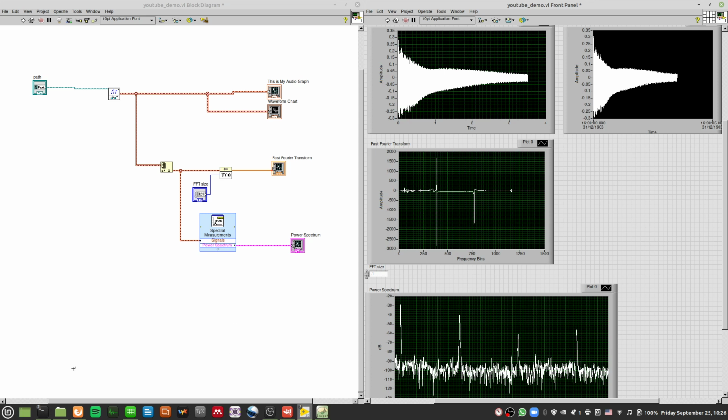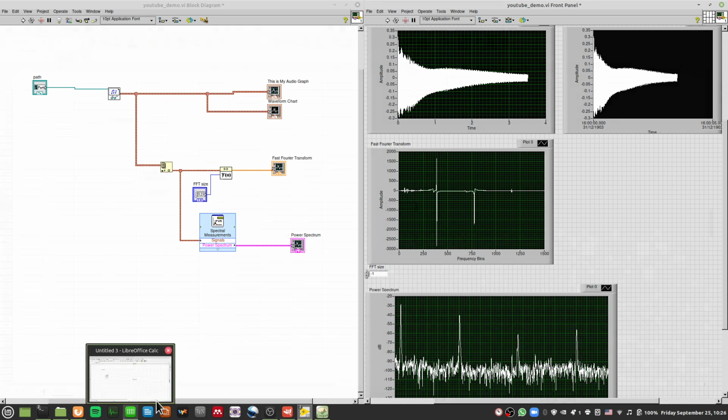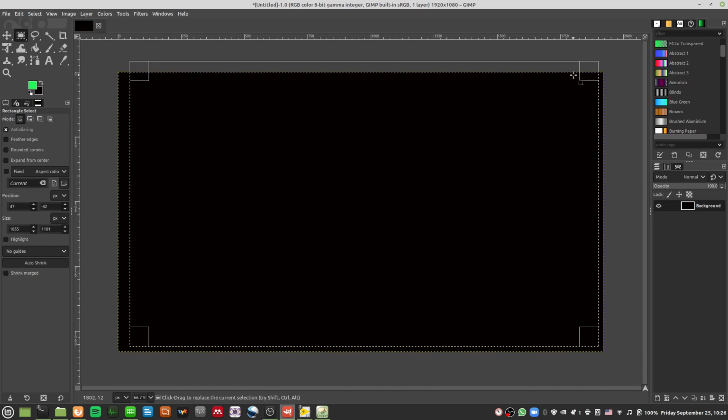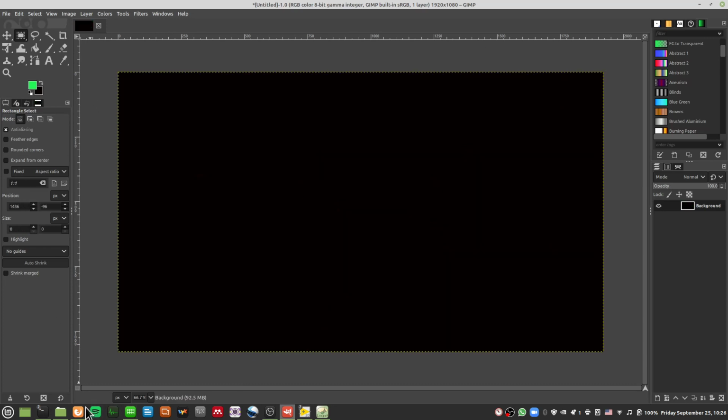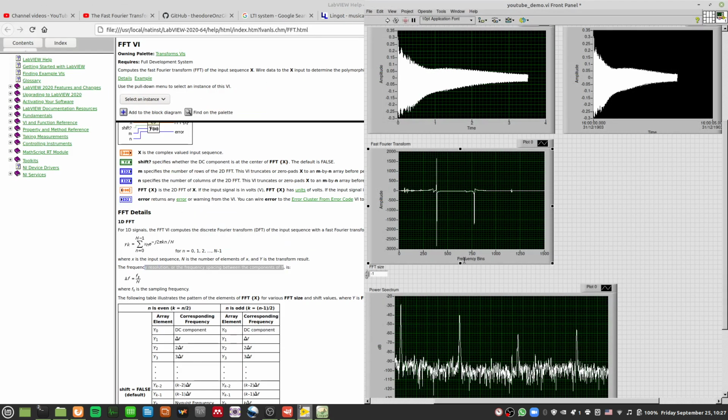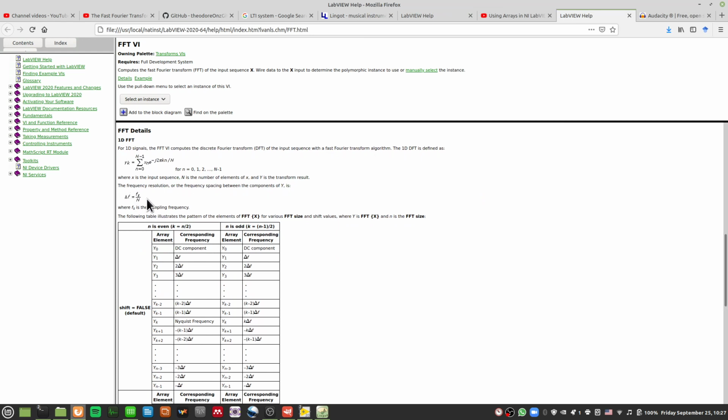So there are a number of workarounds. Remember we were talking about this sampling frequency. We can see this frequency resolution, or the frequency spacing between these frequency bins, between, let's say, bin 249 and 250. What is the number of Hertz changing between 249 and 250? It is going by this formula, which is the sampling frequency over N.